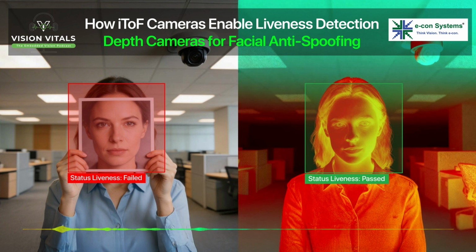Two options. There's a USB interface with UVC compliance, which gives you plug-and-play connectivity with both Windows and Linux systems, so integration into biometric terminals and development platforms is straightforward. And there's a GMSL variant for embedded deployments that need longer cable runs and a more industrial-grade system design. Oh, interesting. So the USB route is great for getting up and running quickly, and GMSL is for the more demanding production setups. Yep, absolutely.